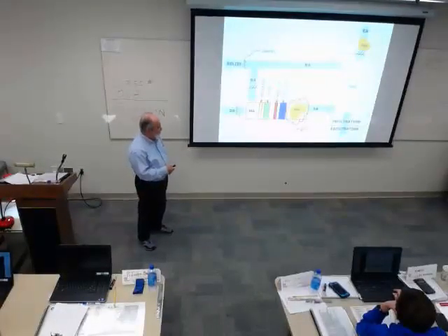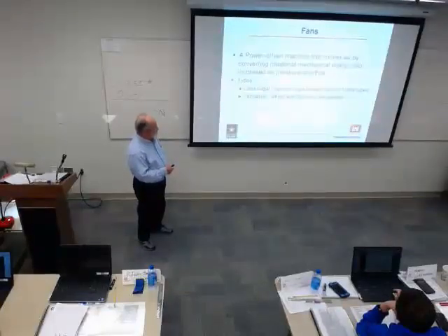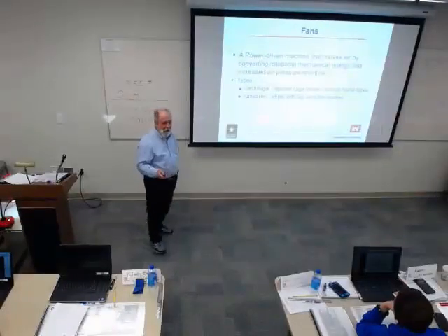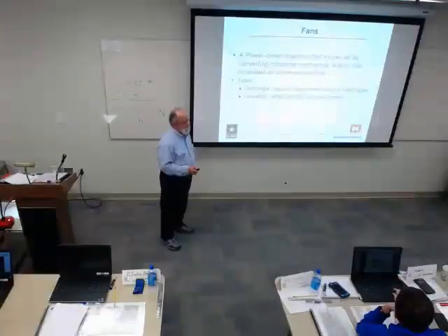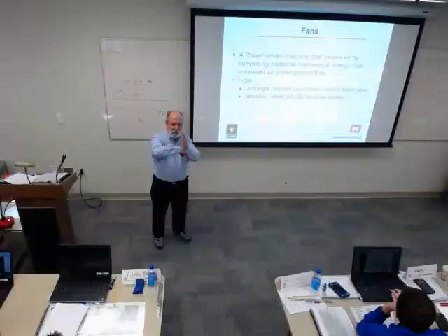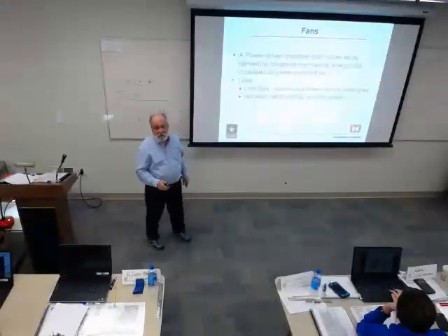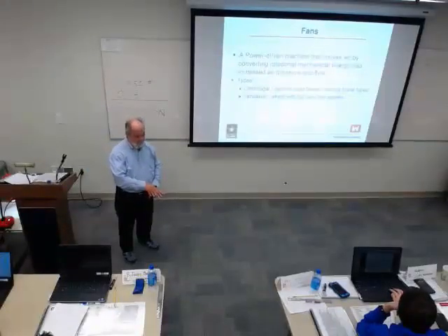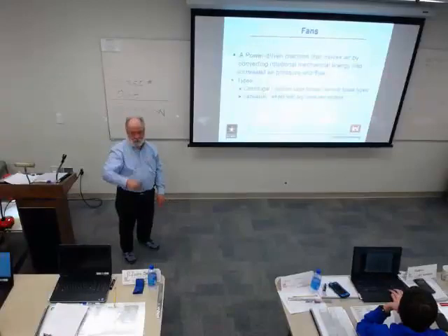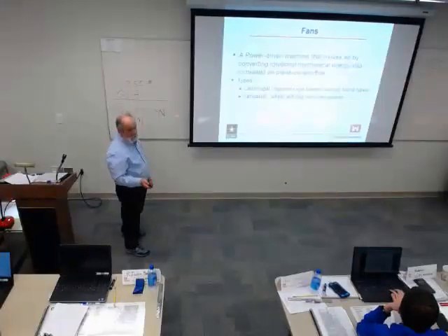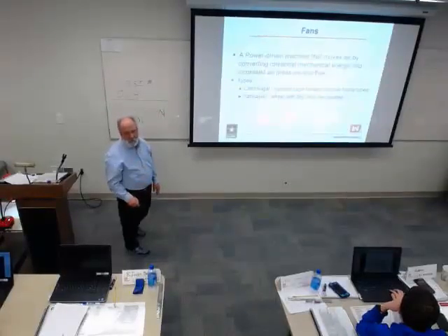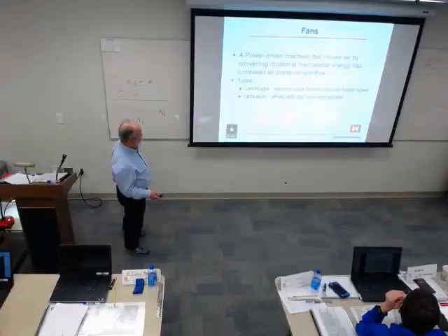And then there's the fan, kind of the heart of our system. It moves air by basically bashing into it and making it move. People say it's centrifugal, that's what we call it, but actually it's another force that makes it move. The air is like this, the fan crashes into it like that, and moves it like that. The air does not necessarily mix as it goes through the air handling unit unless it's way off of its curve. The air goes basically radially out from the center. Very low spinning occurs. That's why, if you have bad stratification, it'll go right through your fan, hit the duct the same way it came in, and go down the ductwork.